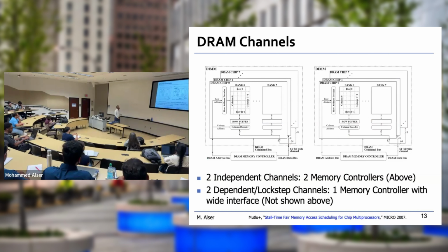All right, so how can we address that? We don't want to build that topology of the network, and we still want to have more DIMMs. We told you that a personal computer's motherboard normally can accommodate 2 or 4 slots for main memory, right? How can the CPU interact with those DIMMs? Every single command dealing with the DRAM should go through the memory controller first. The memory controller is really orchestrating all those commands with the memory device.